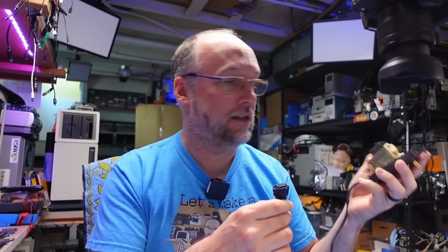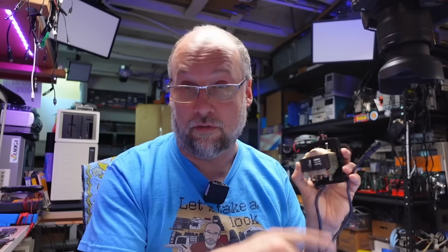So I think it's entirely possible the system might not be booting because it's missing that 60 hertz time signature on whichever AC rail it's using. But it's also quite possible that it needs that other winding for running the modem, and the whole microcontroller is waiting for something there as well. Again, this is where having disassembly of the ROM and understanding what the ROM is trying to do at boot might help me out. So I think the first thing I should really do is get that fuse replaced so I can get this working again, and we can try powering the system up with the large capacitor installed in it again and see if it does something different with this running.